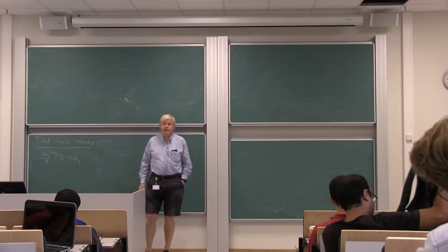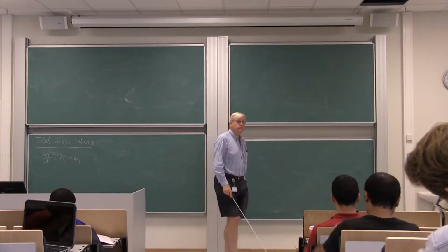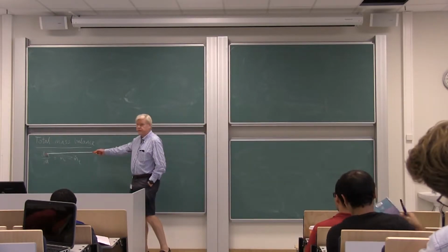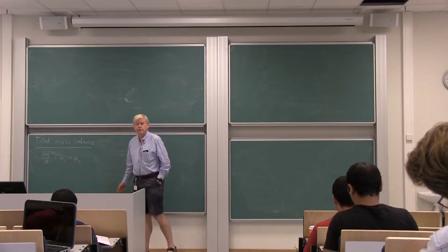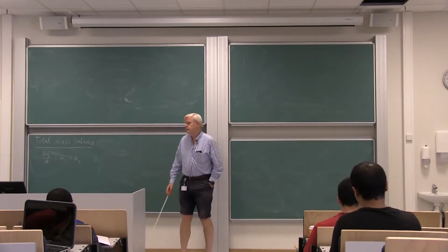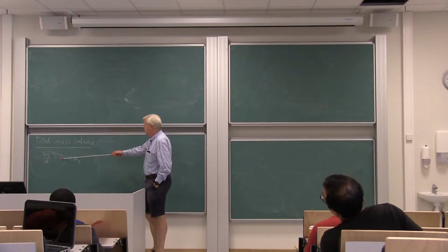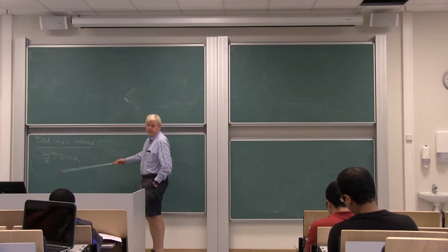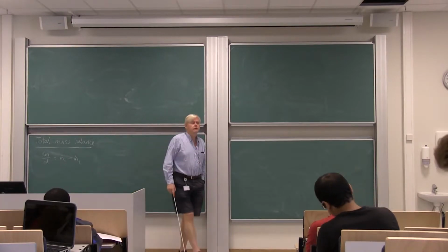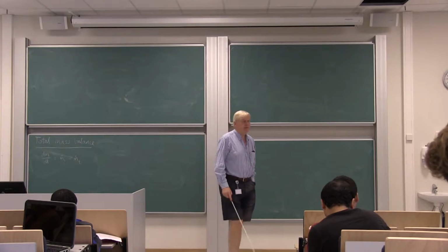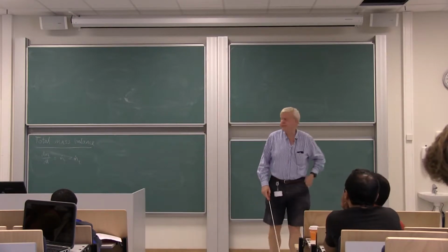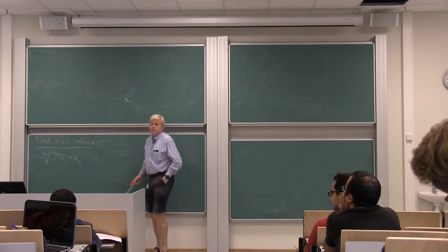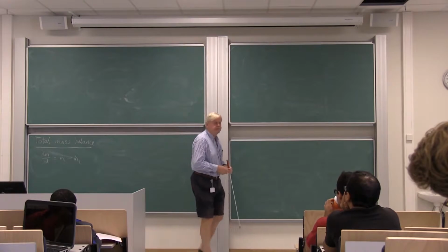M is the total mass in the system. And on the left side we have the time derivative. dm dt is the time derivative of the total mass in the system. And that equals the influent mass flow. So the dot on top of the m means mass flow. In general, the dot on top of an extensive variable means flow. So influent mass flow minus effluent mass flow. So what comes in minus what flows out.